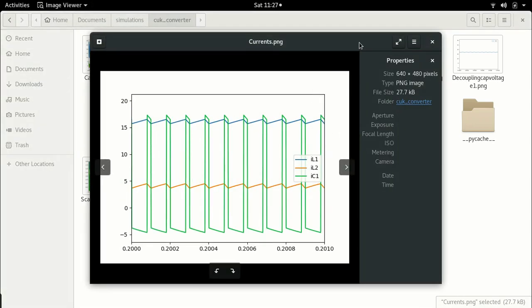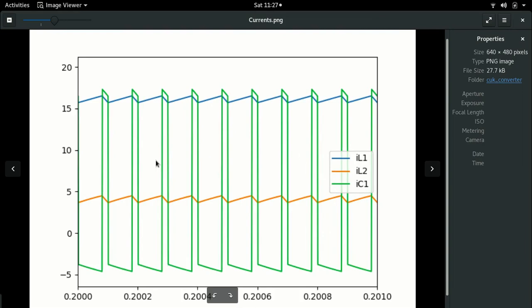And you see, this is exactly a similar plot. The plot is not very different. Only thing is, remember, the capacitor current has slightly decreased because it has now achieved a steady state, right? In almost any converter there is always some kind of an overshoot, and this was the case of an overshoot. So the performance is very similar to what we had before. It's just that the magnitudes are slightly different. I don't think it's necessary to explain it all over again. What's important to understand is, even though we've changed the modulation signal from 0 all the way to 0.8, the performance of the converter still remains consistent, right?